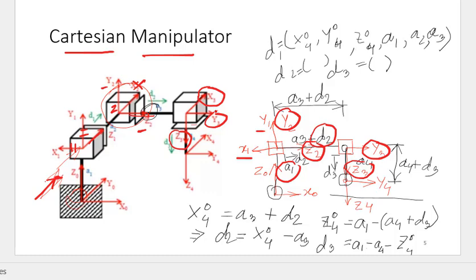And also d3, because this arm can move, displacement, sorry, can move displacement. Also d3 and a4 is the direction this will go. Its total link length is a4 plus d3. This one is a4, and this is a4 plus d3 total.